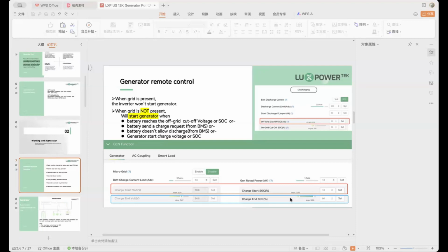In this situation, when you turn off the generator, we have to make sure your battery can take your load and doesn't require a charge. So you have to make your battery ready to discharge. Then we can turn off the generator. Some generators don't support the auto start function, so you have to start them manually.